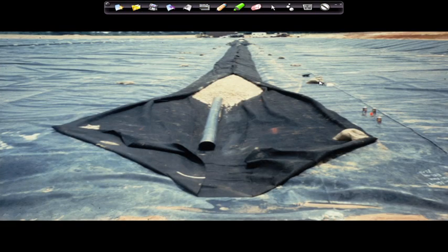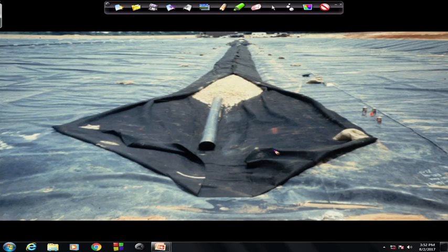So that's the header, that's the middle pipe that you saw, and this is the geotextile that I was talking about. The black part that you see is the geotextile, and then this is the pipe. The pipe has perforations where the leachate is getting collected. That's the sand in there, and it is wrapped in this geotextile to prevent it from getting clogged and to save this pipe from any breakage and all that.